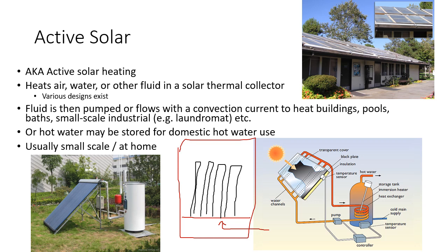And these metal downspouts allow the air from down here to go through them up to this top area where there's an entrance into it. So cold air, let's do blue for cold air. Cold air comes in from my shop, let's say during the winter, heats up in all of these black tubes, and then all of this hot air is going to go back into my shop.